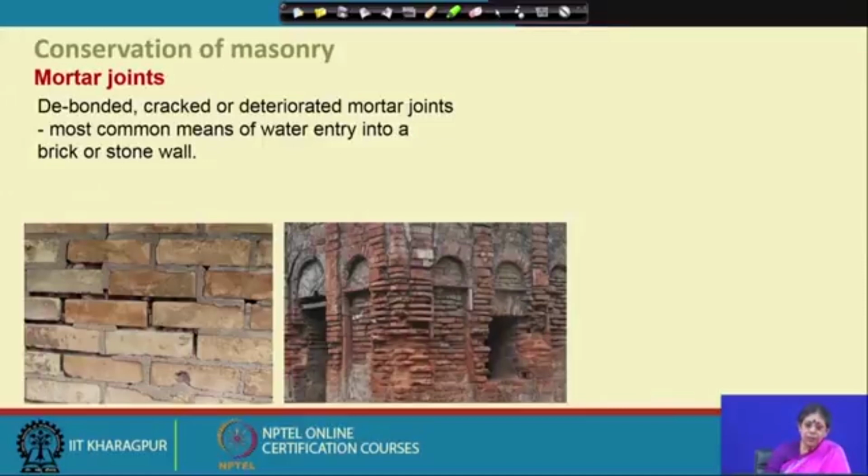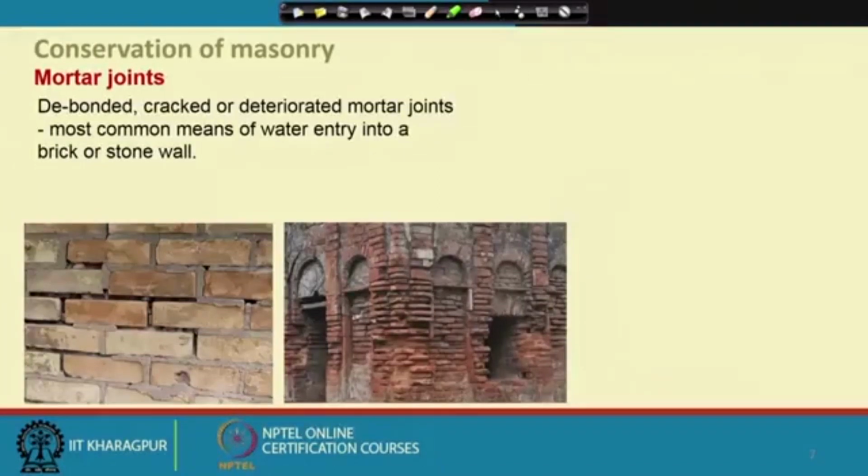First of all, the way it has been done is not proper, the debris has not been cleaned, and it is a stronger material. So with temperature fluctuation and other factors, this is strong. One has a belief that if you use a stronger material for the joining, that is better. It is absolutely wrong, because the joining should hold the thing together, but it shouldn't be stronger, because in that case the original material itself, the brick, deteriorates faster. The joints are a stronger material, and they do not behave in unison with the temperature fluctuation and other things, and it cannot breathe.